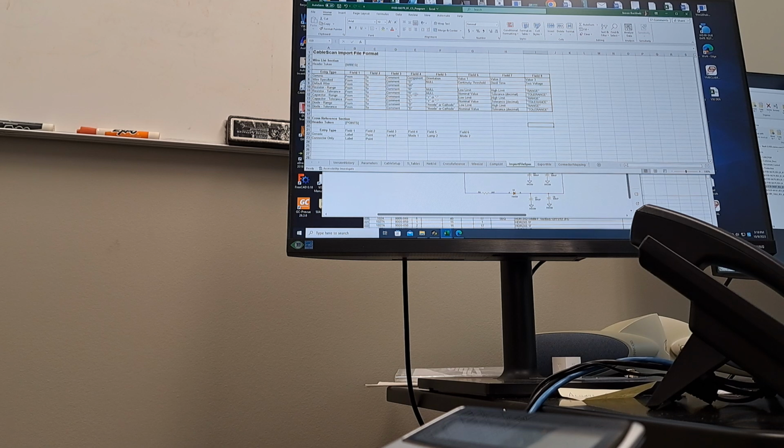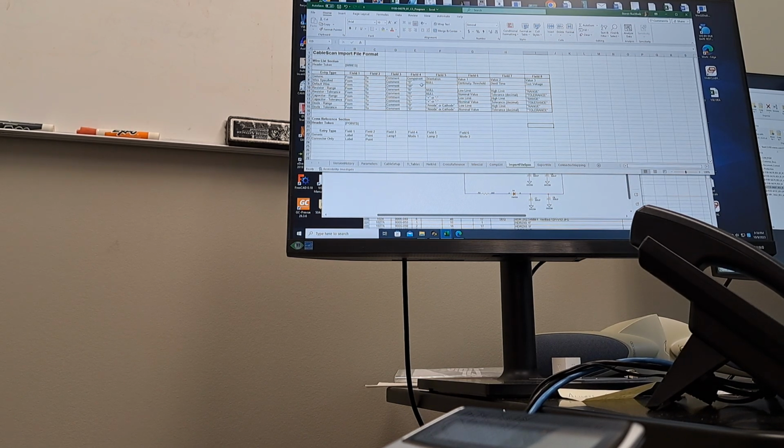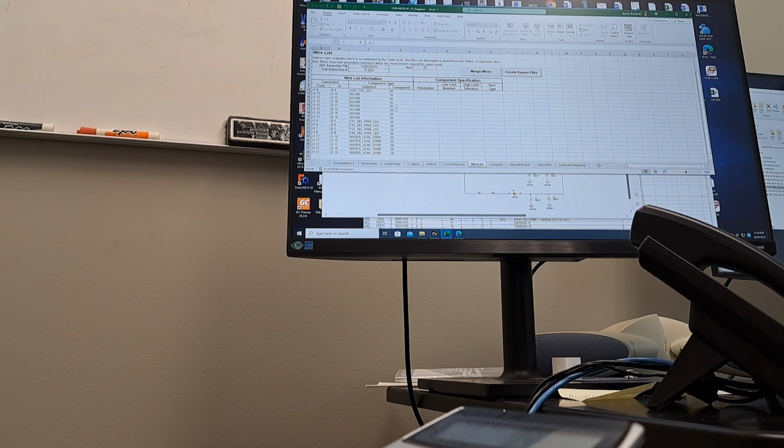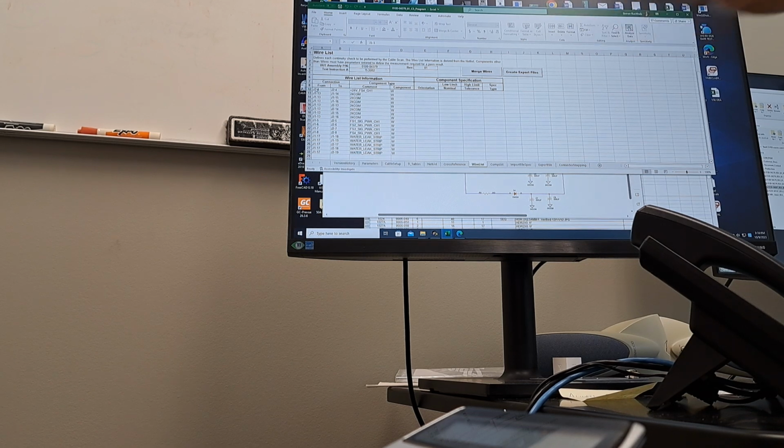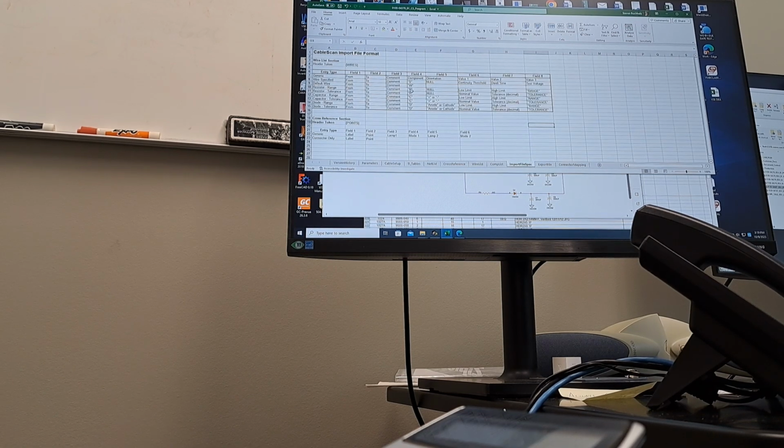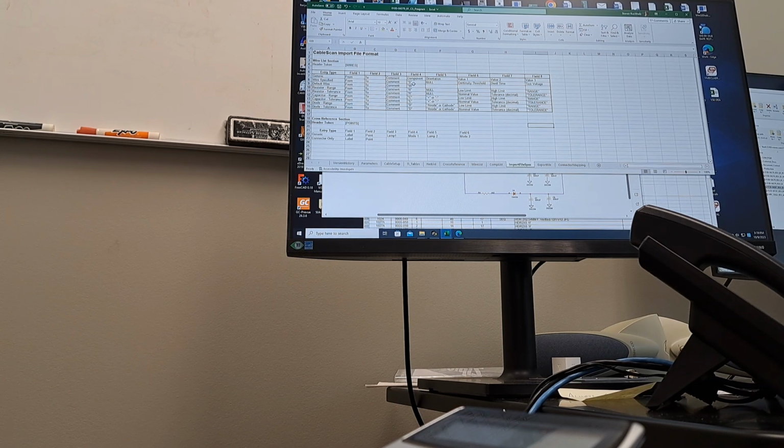So this is stuff that is for cable scan. So if you wanted to add a wire, if we look here, see how it's got the component type as a W. So this is saying that all of these are just wires. They're point-to-point connections. Okay, and this was the thing I was looking for before. So you can do wires, and then there's a different kind of wire here where you can give it continuity threshold, dwell time, test voltage. I've never used that.